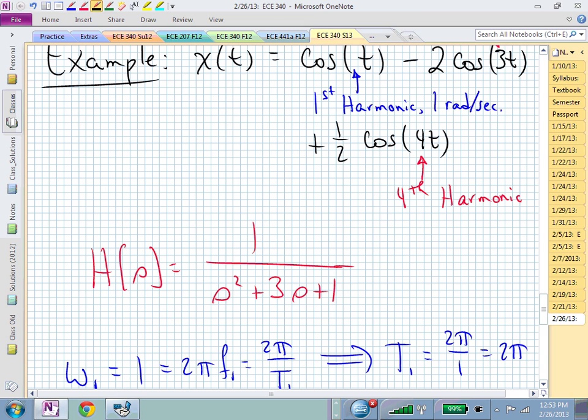Well, here's a quick trick if you don't already know it. All you really have to do, if the leading coefficient has been normalized to 1, is look and see if these two coefficients are present and if they're positive. If they're both there, and both positive, you can immediately say those are going to have negative real parts. Whether they're complex or real, I don't care, but they're going to be in the left half S-plane. That transfer function is stable.